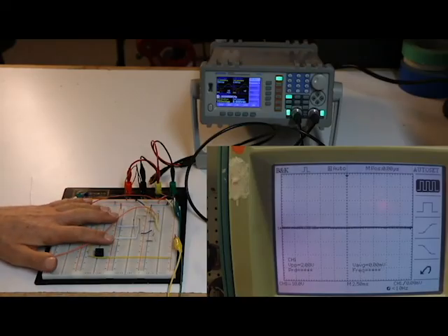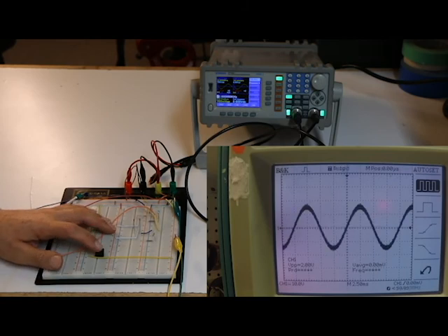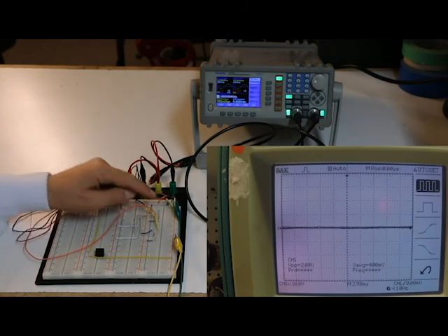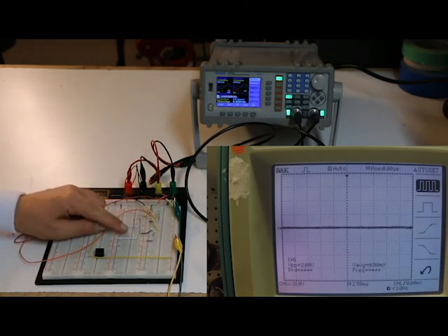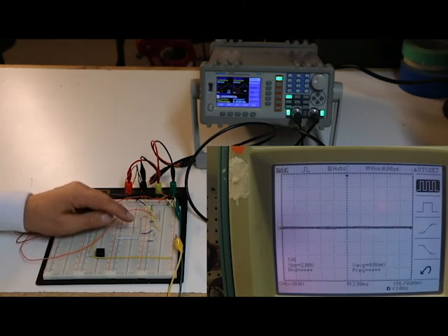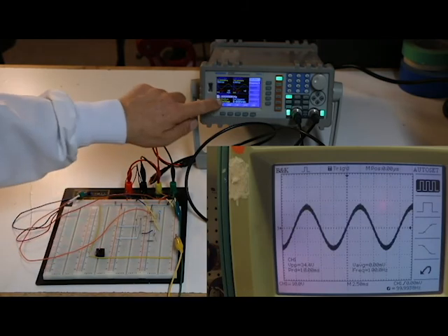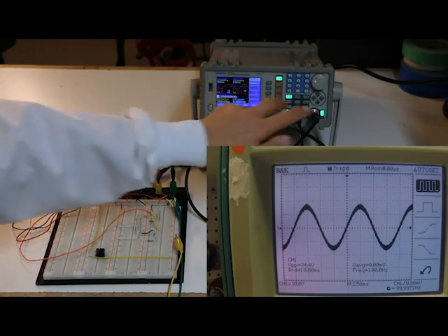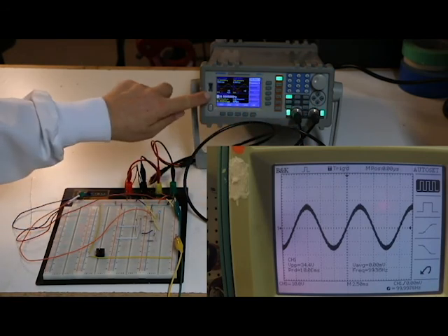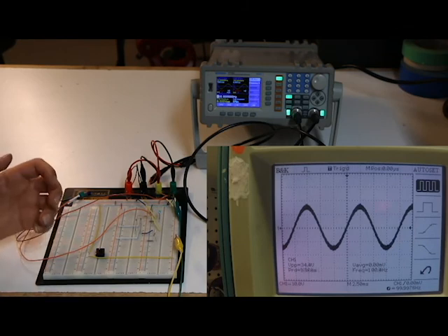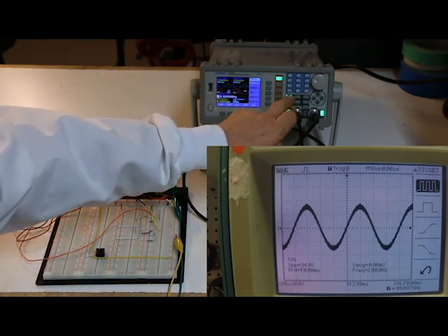So here's our filter circuit. I have the option of looking at it raw, like that, or I can look at one filter or the other. That's the high-pass filter, that's the low-pass filter. This is my 0.47 microfarads, and these are 10 picofarads together in parallel, so I now have 20 picofarads. Cool, so now let's take a look at the raw waveform. That is the 12 kilohertz, and also, if I go over here to the other channel, that's the 100 hertz. The 100 hertz is the actual waveform that you see there, the big one. And then the one that seems a little thicker, what that actually is, let's go over to here to channel.